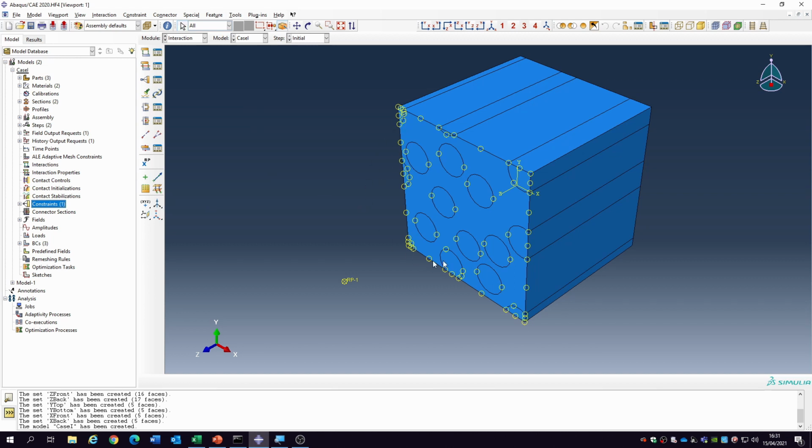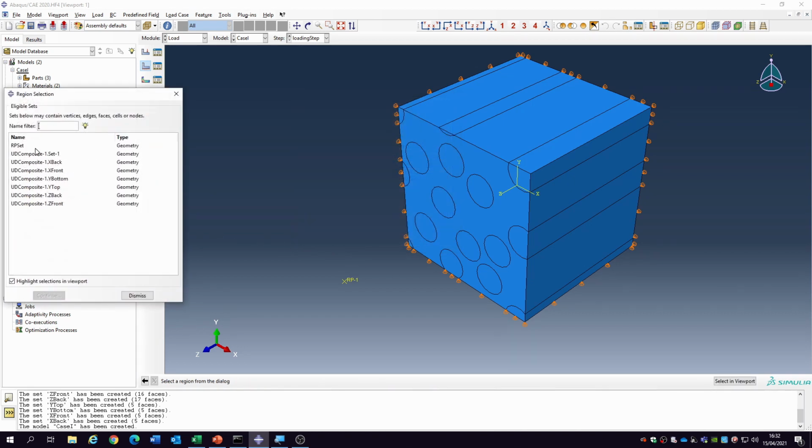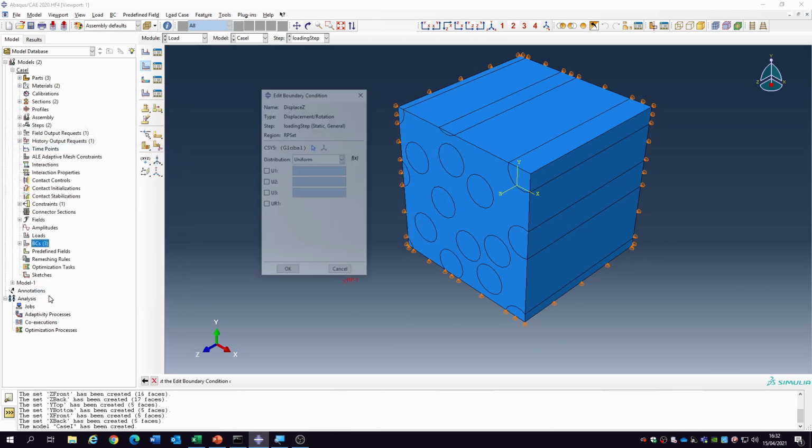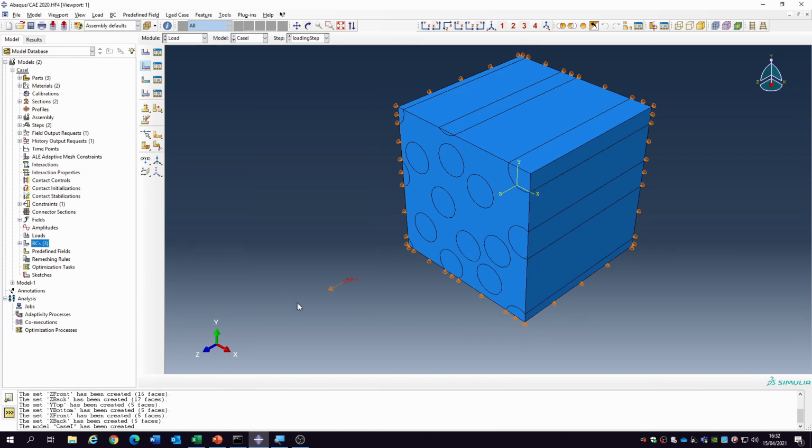So basically we specified a star equation here linking this point to that point, so that if we then go ahead and say, okay, we're going to apply a displacement load, so displace Z, in the loading direction displacement, we can attach it to this reference node. Okay, and we're moving it in the Z direction. The system was 100 meters, so a strain of 10% will mean a displacement of 10. So you can see what has happened here. We apply the load here, and this load will be translated to what's happening in there.